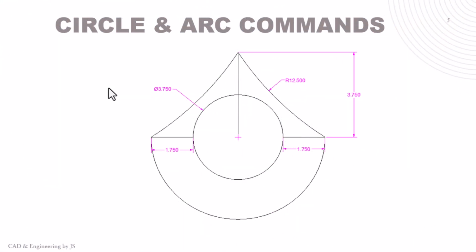As we just reviewed, there are many options to draw arcs, but in general, you will find that using circles is easier than arcs, starting with the fact that you don't have to consider the direction in which you're creating the object. And you can also use circles and then use some other editing commands like trim in order to finish your task. I leave you with one exercise for you to practice.